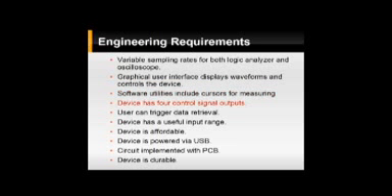The device will also provide the students with 4 control signal outputs, which will be ground, 1.8 volts, 3.3 volts, and 5 volts, as is typical with digital signals. The user can also control how data is triggered off of either the rising edge or the falling edge. We will also provide the students with a useful voltage input range of plus or minus 25 volts.